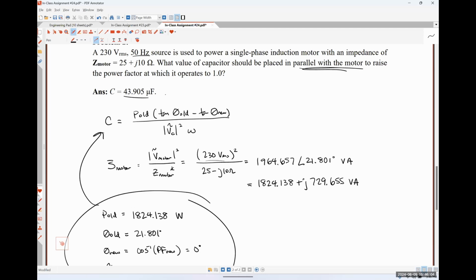So the reactive power, I'm not entirely sure that I understand your question being power with respect to the angle, but the reactive power represents what's going on with temporary energy storage effectively. So it's associated only with inductances and capacitances. Inductors absorb reactive power and capacitors supply reactive power.